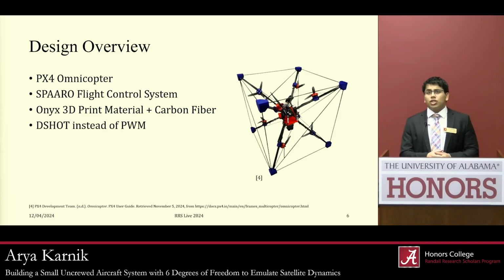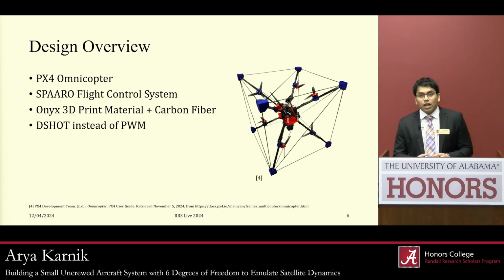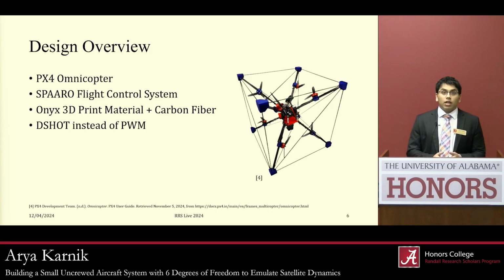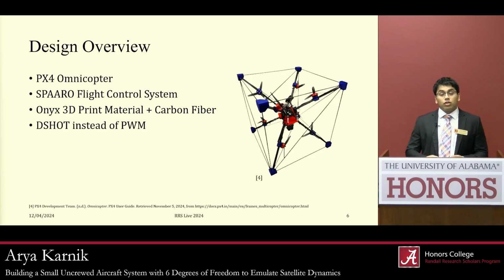We are also using the D-Shot protocol instead of PWM. And PWM stands for pulse width modulation. These are both technically digital signals, but D-Shot is, in essence, a true digital signal. And for the purposes of this presentation, it essentially boils down to the fact that PWM suffers from things like jitter and also needs calibration, while D-Shot is straight ones and zeros.